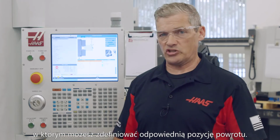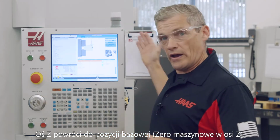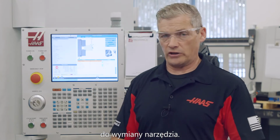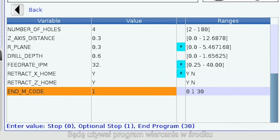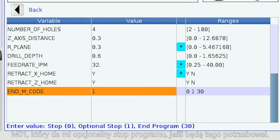Retract Z home works the same way, except now we're controlling the Z-axis. I'll leave this set to Y as well, so the Z-axis retracts all the way home. Here also, entering N will open another line where you can enter the particular Z-axis position you want if you want it to retract a shorter distance before the next tool change. The final line selects the M code we'll end the program with. Since I'm going to use this drilling program in the middle of my larger part program, and I'll be adding a tapping cycle right after it, I'll select M01 to give me an optional stop if I need it.